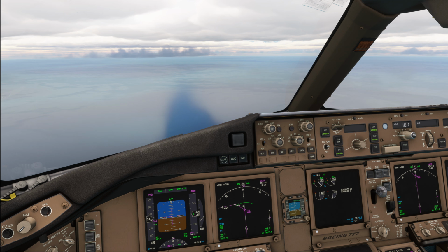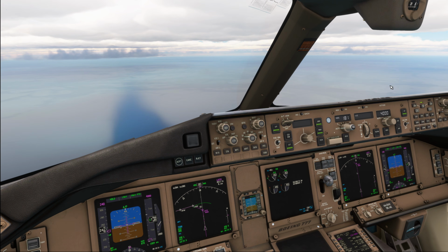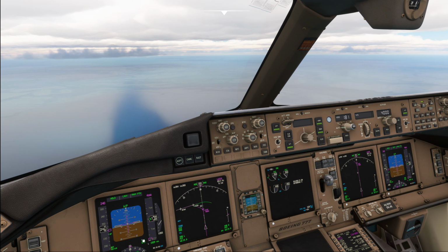Approximately 2 miles prior to the descent point or the final approach fix as applicable, we are going to call approaching glide path, select the altitude down to our minimums, select or verify VNAV, and select or verify speed intervention with an appropriate speed set.